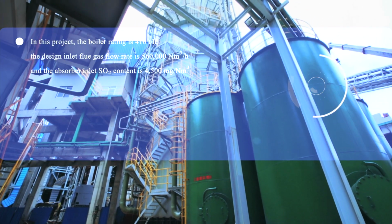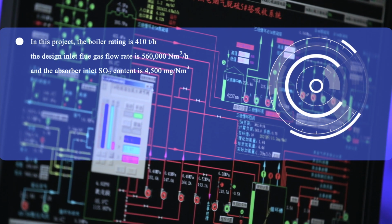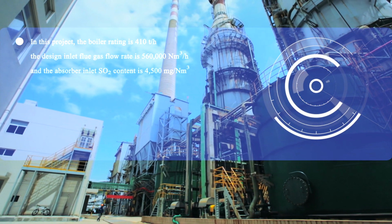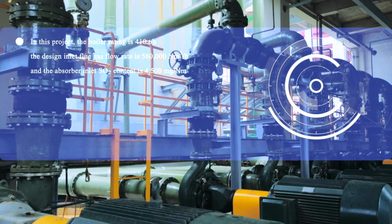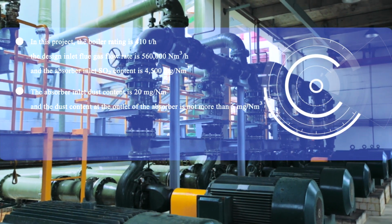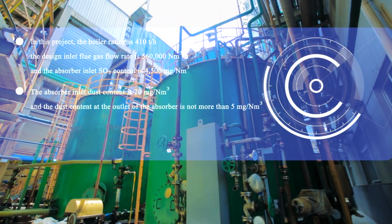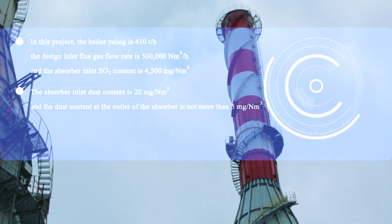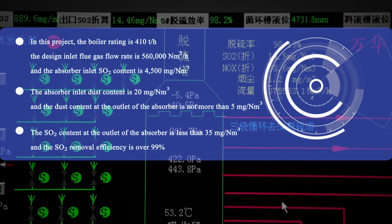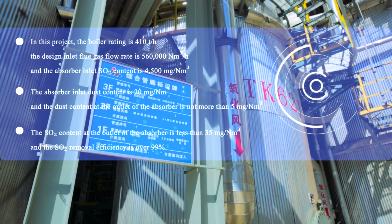In this project, the boiler rating is 410 ton per hour. The design inlet flue gas flow rate is 560,000 normal cubic meter per hour, and the absorber inlet sulfur dioxide content is 4,500 mg per normal cubic meter. The absorber inlet dust content is 20 mg per normal cubic meter, and the dust content at the outlet of the absorber is not more than 5 mg per normal cubic meter. The sulfur dioxide content at the outlet of the absorber is less than 35 mg per normal cubic meter, and the sulfur dioxide removal efficiency is over 99%.